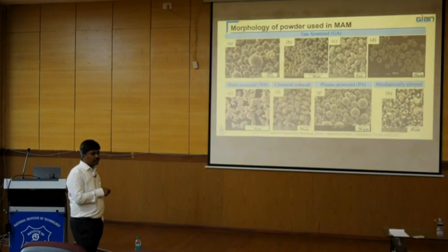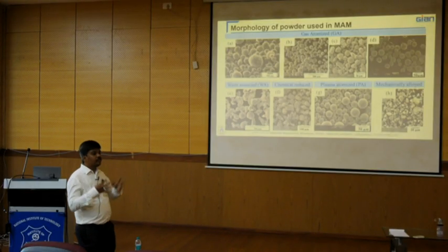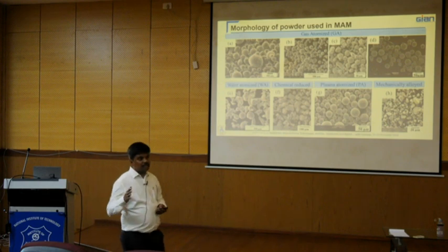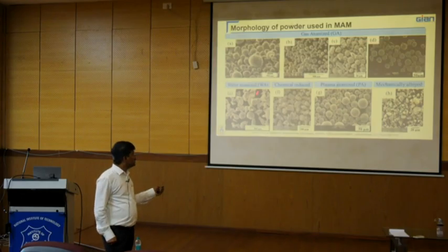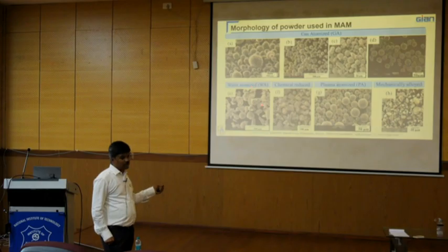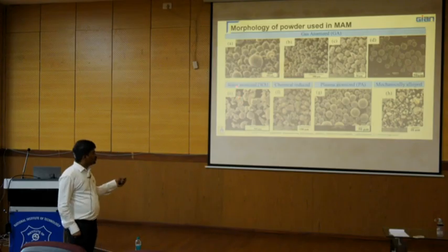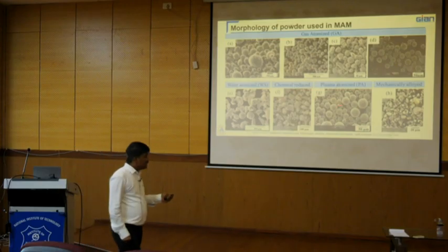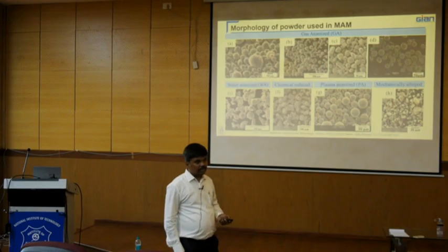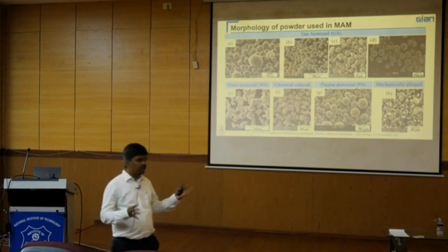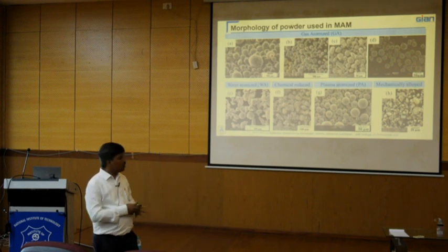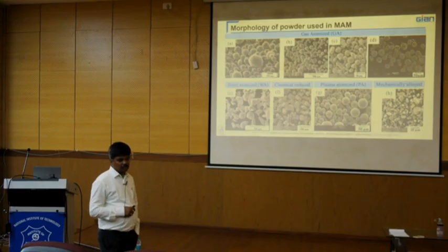Non-spherical powder particles can also be obtained, because this depends on the solidification. In water atomization, rapid quenching takes place compared with the plasma atomization process. The rate of cooling is different in gas atomization and water atomization. Because of that, some irregular powder particles also get solidified. And in the chemical reduction process, we get spongy-like structures in the chemically produced powder particles. By chemical reactions, we can extract the powder particles from ore. Those powder particles do not have spherical shapes.